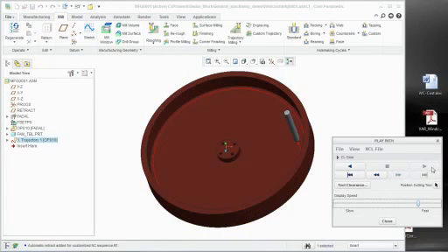And that really is the power of using Pro-E models with the PTC software, because again, since they're all connected, if a design engineer at any point in time throws a change at you, instead of rebuilding all those toolpaths or exporting IGES files and STEP files into other software and then having to recreate them or trying to tie everything back together, as long as it's a change, you have the ability to come in and make that change, go back to your machining software, do a regeneration, and any toolpath that was created against it will update as long as it's capable. There are a few limitations, but as long as it's capable of working, it will work.